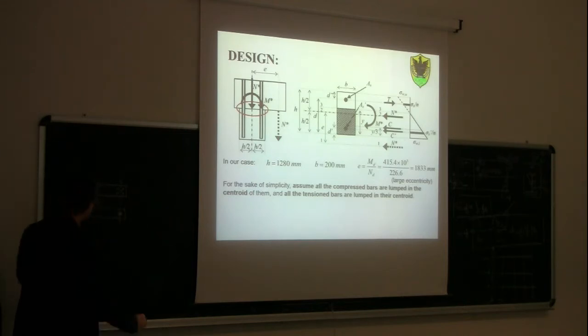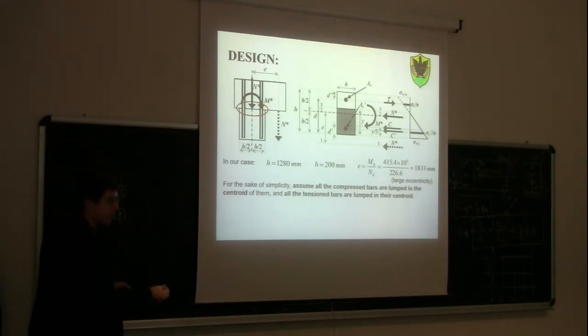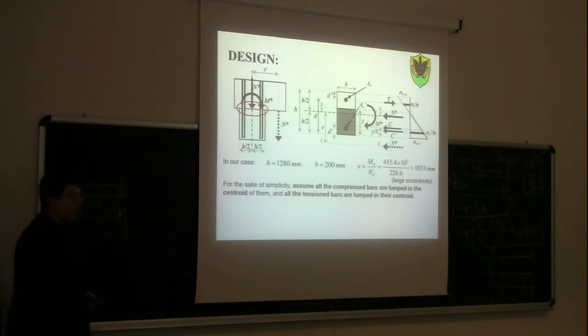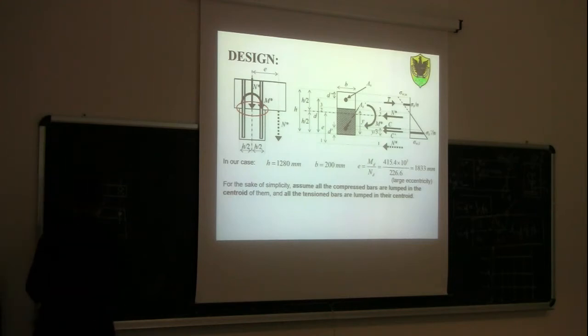So what we do is move from this cross section to this cross section. On this cross section we solve and find out, for example, the neutral axis, y. So we use the same equation as before. Once we have concentrated the 4 bars into only 1 point, we use the same equation as seen before to calculate the neutral axis, which was, I think, x, to find y. And then when we calculate the stresses in the rebar, we would have, for example, a stress distribution like this.